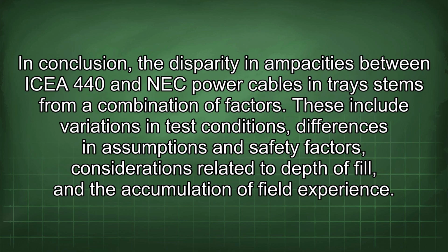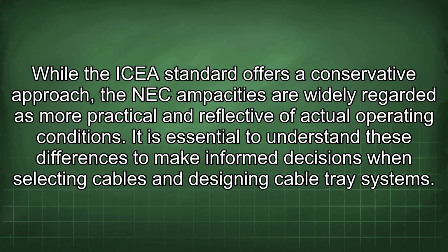In conclusion, the disparity in ampacities between ICEA 440 and NEC power cables and trays stems from a combination of factors. These include variations in test conditions, differences in assumptions and safety factors, considerations related to depth of fill, and the accumulation of field experience. While the ICEA standard offers a conservative approach, the NEC ampacities are widely regarded as more practical and reflective of actual operating conditions. It is essential to understand these differences to make informed decisions when selecting cables and designing cable